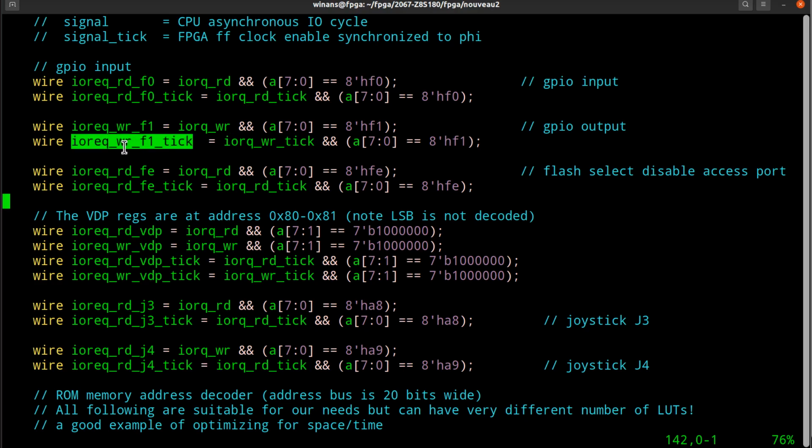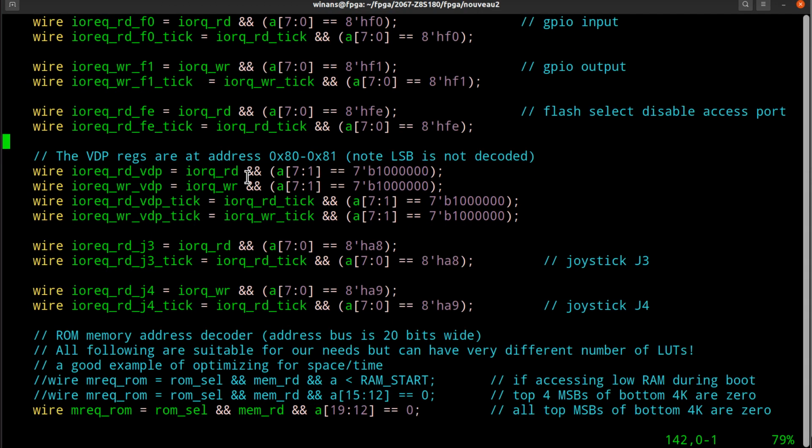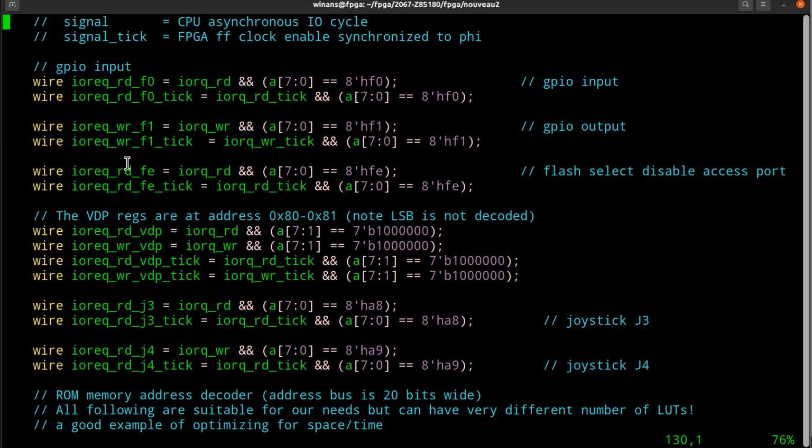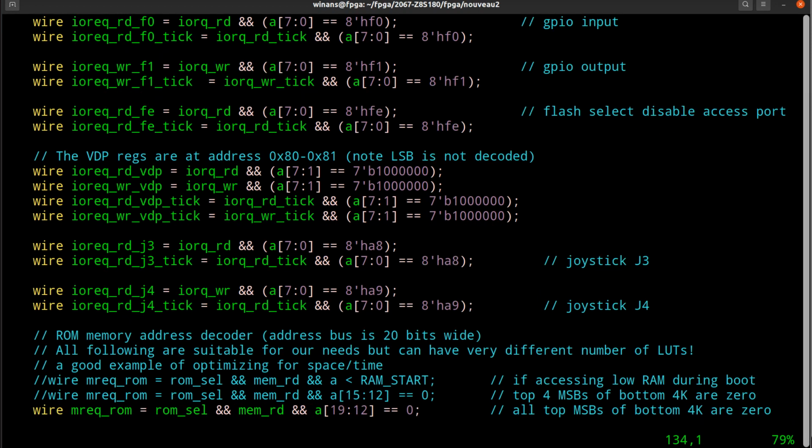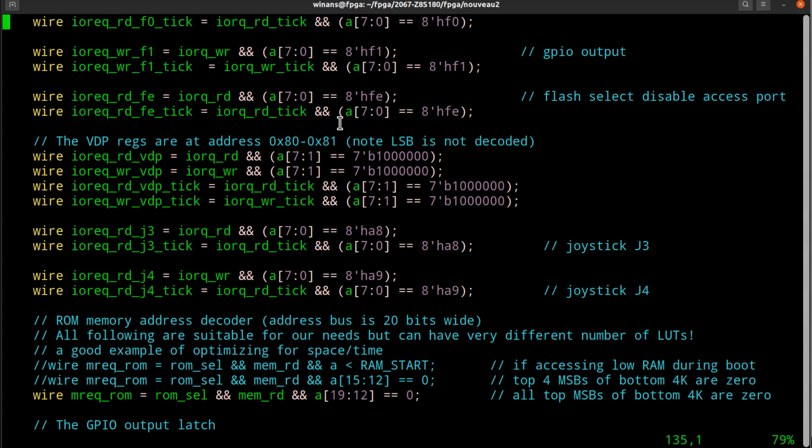And this one here is the reduced window size. I don't necessarily use all these things, but I made them consistent because sometimes I want both, and other times I only want one. So in this particular design, I got three different latches. FE is the latch I mentioned above that shuts off that shadow ROM, and I want to be able to do that at some point. It turns out you could use either one of these for that because synchronizing that particular situation is not critical.